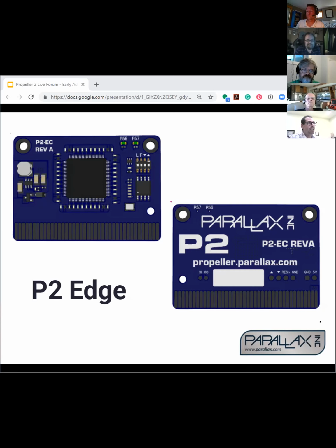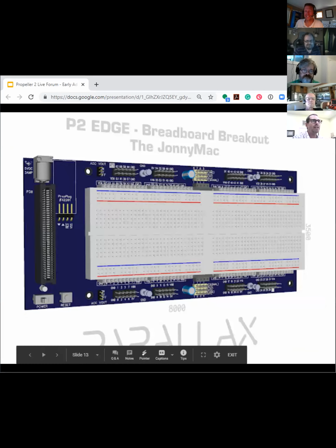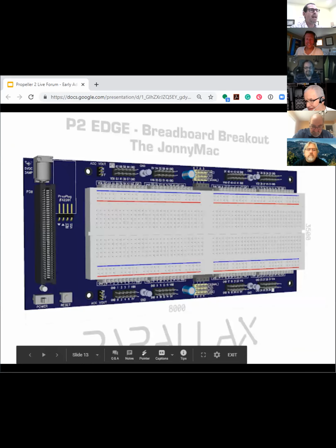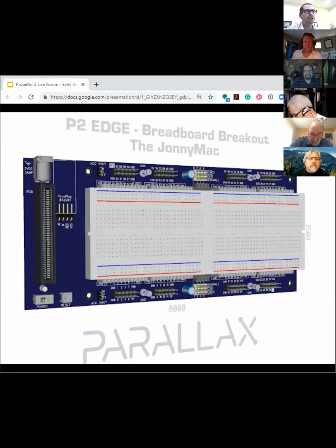And by the way, Jan Omani on the forum messaged me and said that he discovered that TI makes these little chips. They're like 20 cents each, and they are super low impedance muxes. And they take like several 10 microseconds to switch. And I realized what they are is they're simply an NMOS, an NFET, between A and B. And the reason it takes long to turn on is because they have a charge pump on there that super biases the gate voltage on that NFET to make it like an 11 ohm connection between A and B. And then it's set up in a mux fashion.